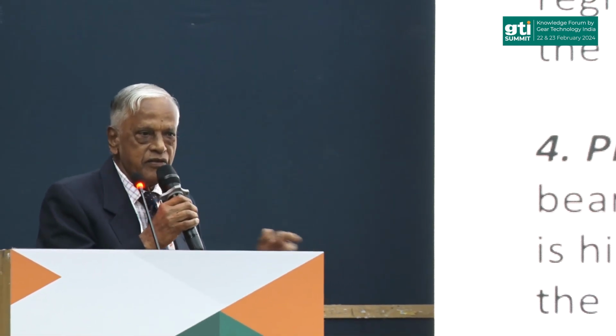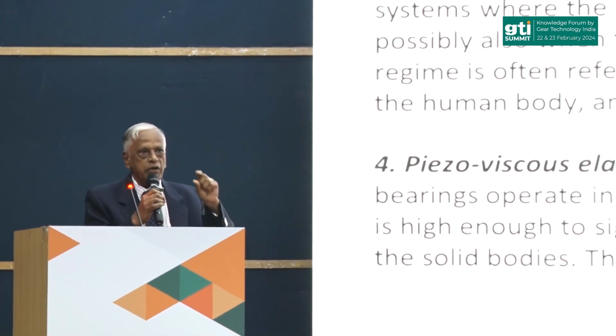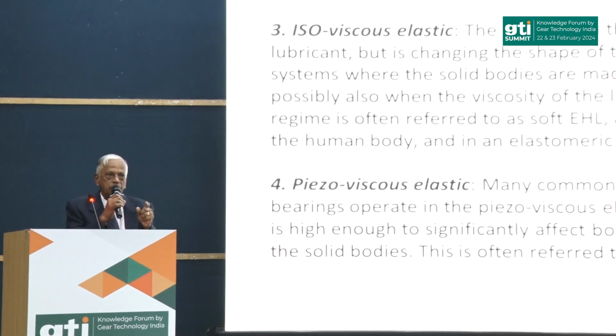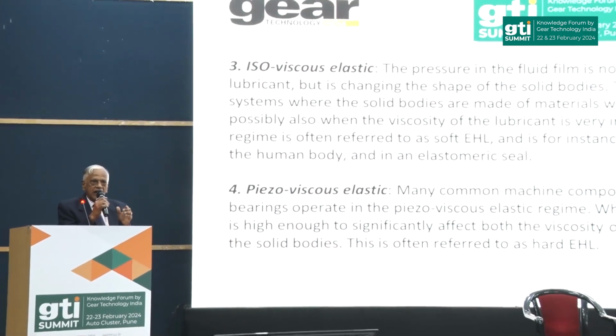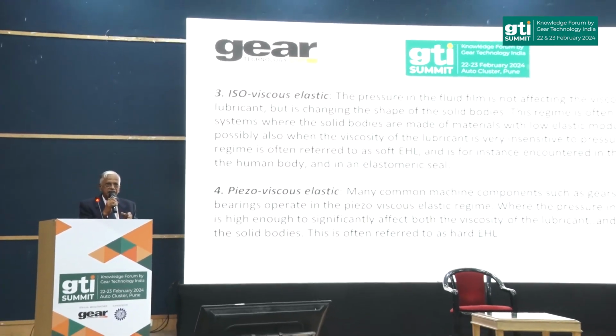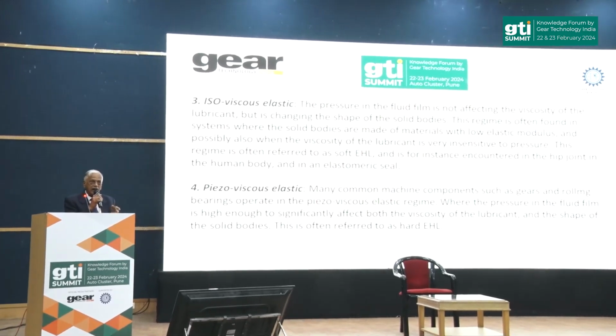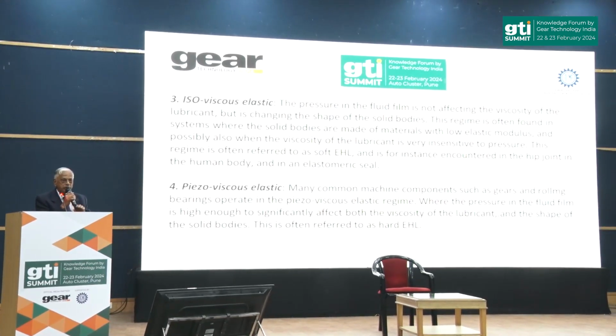This, I can skip it also. You will know there are different kinds of regimes known as iso-viscous rigid, piezo-viscous rigid, iso-viscous elastic, and piezo-viscous elastic. You can always read it if you want, but I don't want to read it. Between the two, when the load is applied on the tooth flank in the presence of lubricant, the load is shared by the lubricant as well as the driven material member.